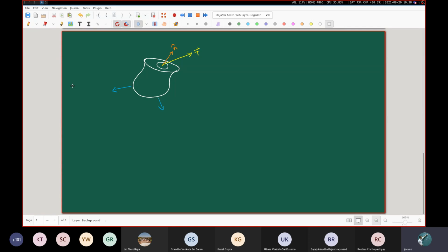Now, you see, I have this general traction vector, this unit outward normal to the cutting plane under consideration. And what I want to say now is that this traction vector can be decomposed into its components in at least two different ways. Okay, so the T vector can be decomposed in two ways. One of them you are already familiar with, you know that even without me telling you anything. One of them is that you decompose this traction vector along the X, Y, and Z coordinates.